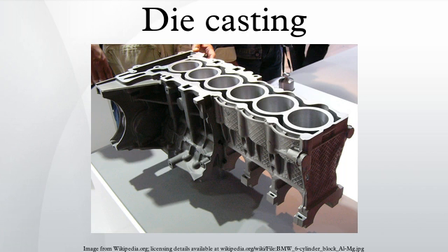The main disadvantage to die casting is the very high capital cost. Both the casting equipment required and the dies and related components are very costly, as compared to most other casting processes. Therefore, to make die casting an economic process, a large production volume is needed. Other disadvantages are that the process is limited to high fluidity metals, and casting weights must be between 30 grams and 10 kg. In the standard die casting process, the final casting will have a small amount of porosity. This prevents any heat treating or welding, because the heat causes the gas in the pores to expand, which causes micro cracks inside the part and exfoliation of the surface.